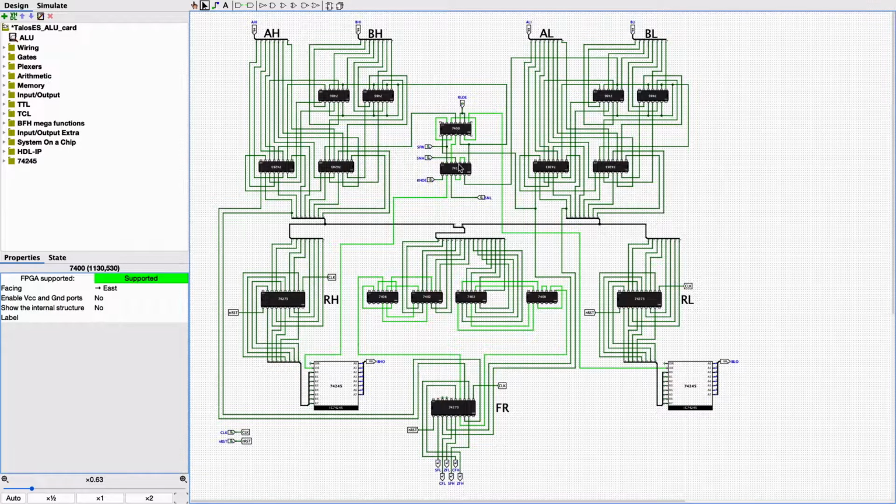Now if we open up these chips here to see the internal logic, yes, this is just 6 inverters, and I am on purpose using the 7414 as opposed to the 7404 because the 14 has Schmitt trigger inputs with hysteresis, and that's quite important on a large design using multiple cards like this in order to take away some of the interference on the input and to boost the signal.